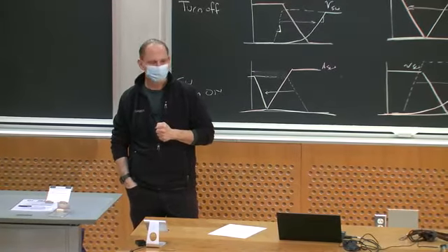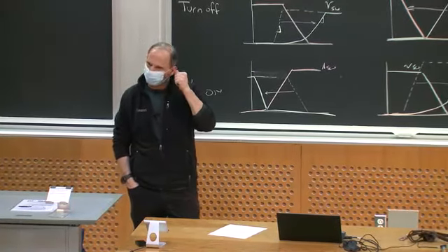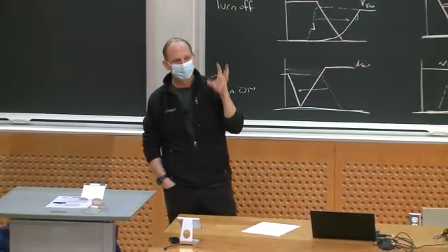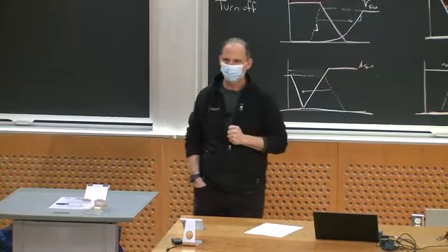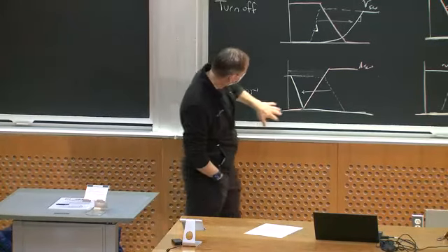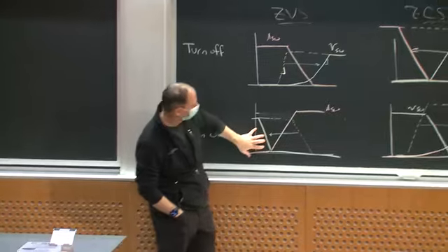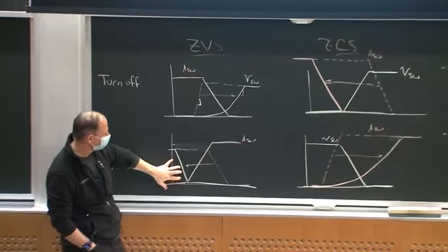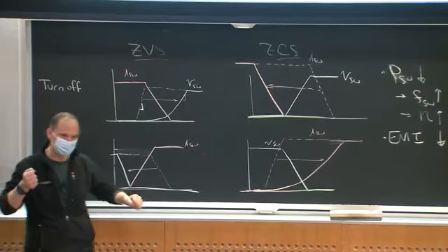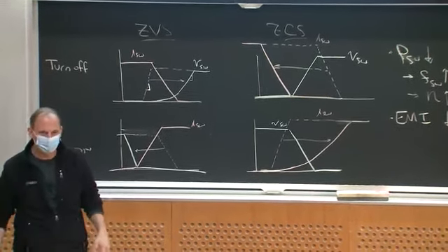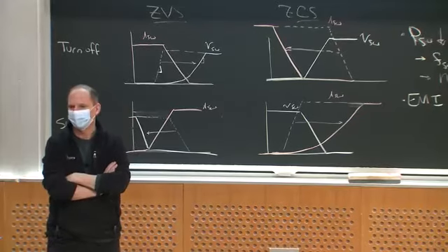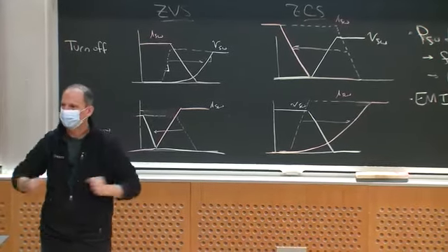That usually means that the circuit's component values, the whole control scheme, everything is geared around meeting the requirements of soft switching. Why? Because maybe I have to make the circuit do something magic, and I only want to turn the switch on when the voltage is already 0 across the switch, so that prevents me from just doing standard fixed frequency PWM. So that's one very broad category of circuits.